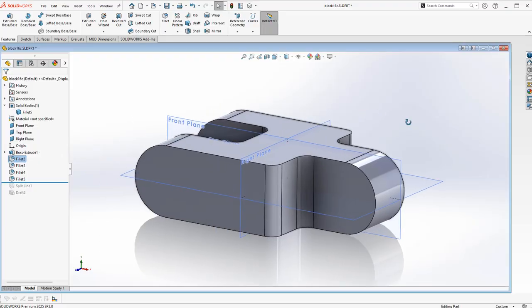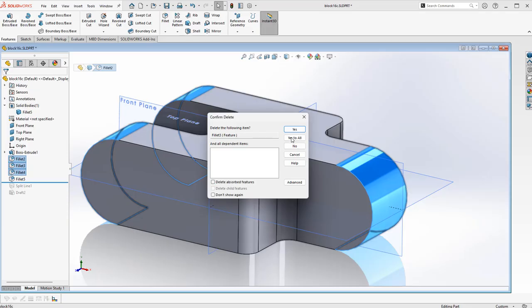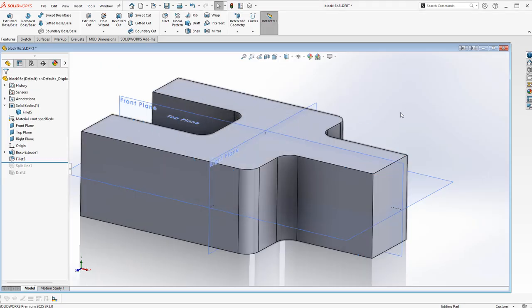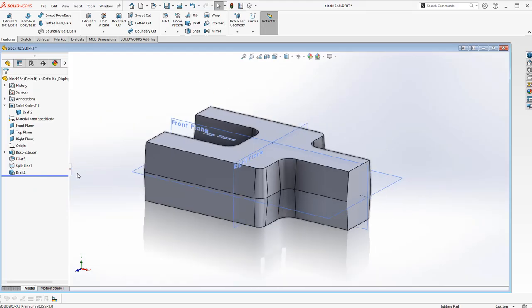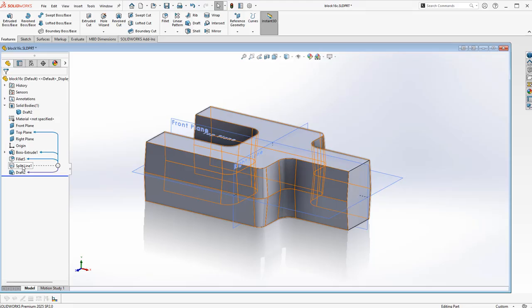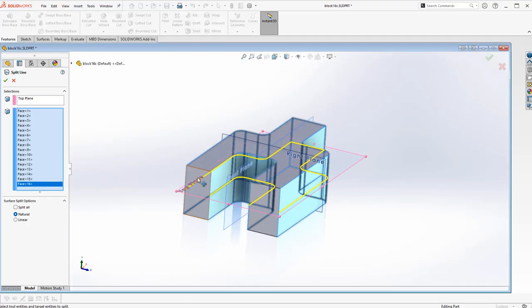So what I'm trying to get to here is, being an R&D person where you're just going to 3D print, this might not be an effective way to think about your process. Now that we're going to turn this into a die-cast aluminum part, I end up deleting all these faces. Look, my draft didn't go away. But I could redefine this split line to include the other faces.